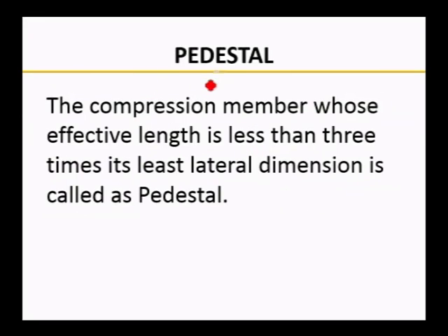Again, the definition of pedestal is a compression member whose effective length is less than 3 times its lateral dimension. If you want to differentiate between the column and pedestal, it is related to the effective length to least lateral dimension.